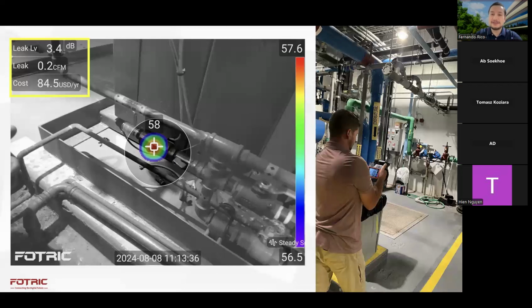And this gave me the insight that finding small leaks is as important as finding big ones. Because if you only have a listening device, you hear something, you say, oh, there's a leak, we have to repair, we have to fix. You may waste your time and energy fixing a smaller one where around there might be a larger one. So the cost estimation tool is a great way to prioritize your work and your repair activities.